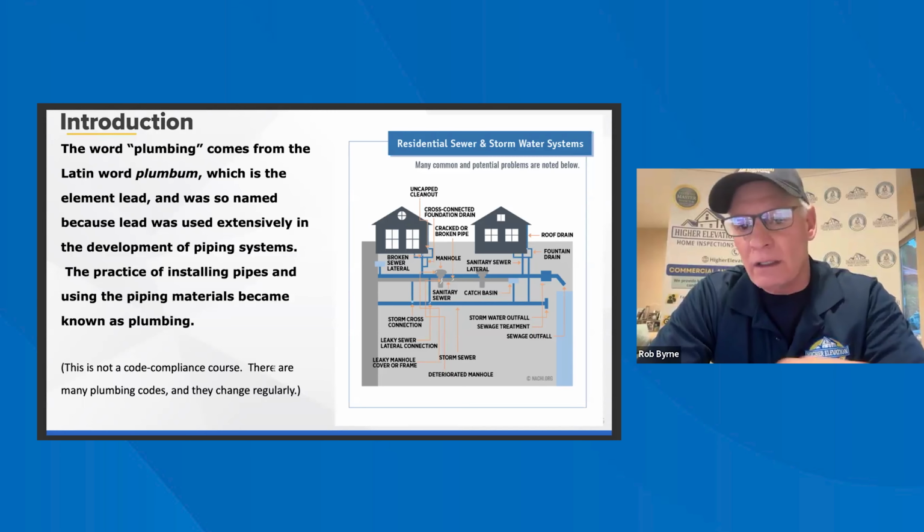This one is a concentric pipe with the intake and the exhaust on the entire run. So this is on the outside, obviously, and it's drawing air in from the back part of this cone shape, and the exhaust is coming out through here. That would be this one here, A. So understand when you're venting it, it's direct vent, and these are the different ways that the tankless water heaters vent. So you'll be familiar with those.